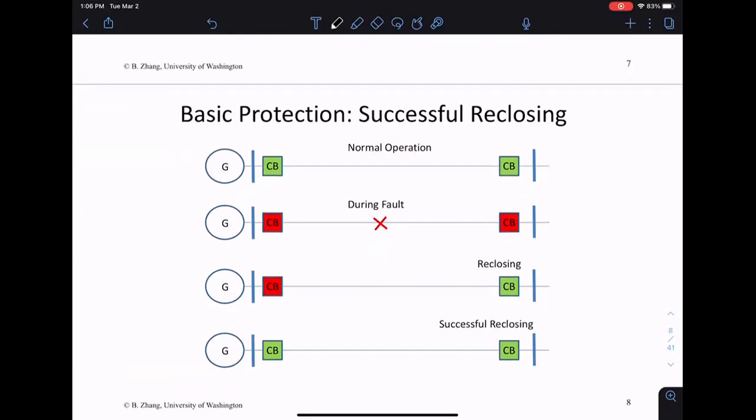Both breakers open. Then the right-hand side will try to close. If it is able, then the left-hand side will close. This is a dedicated sequence. Any questions about this closing sequence?